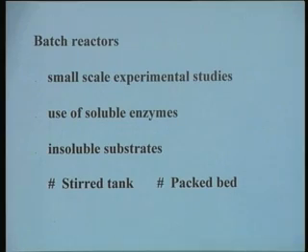And of course, the kind of reactor system that I described a little earlier, for experimental purposes, falls under the batch category. That means the batch reactors are very suitable for small scale experimental studies, mainly because they are simple in construction and operation, and they do not need any supporting structure, unlike in the case of, let us say, continuous reactors, where you need to feed the substrate stream continuously.